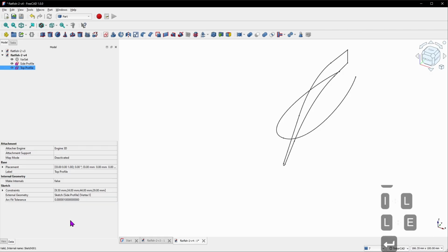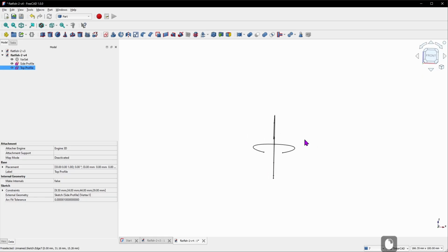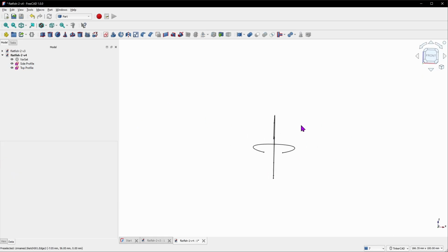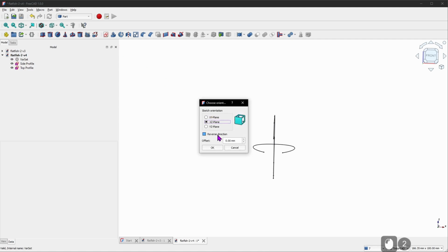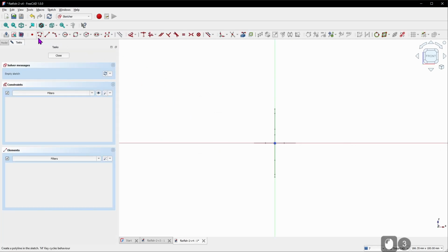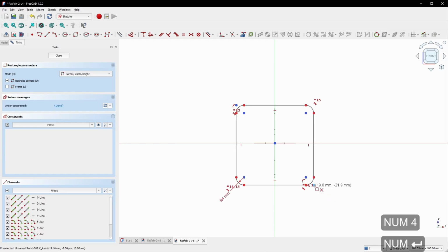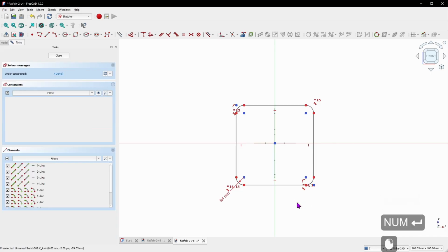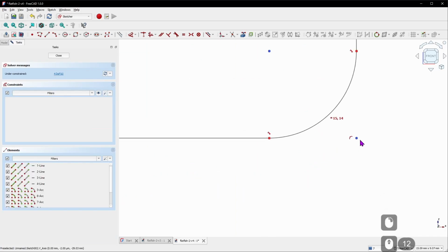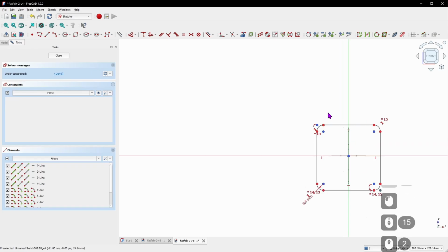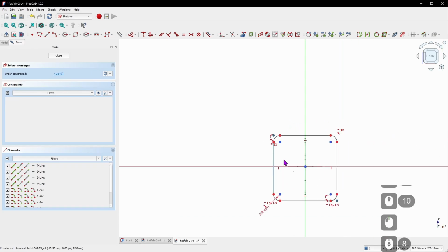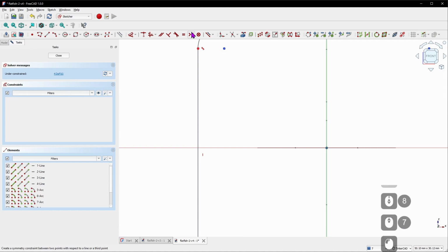We're going to be using the curved array from the curved shapes workbench again. And so we need one more profile, which is going to be the front profile. Let's create a new sketch for the front profile on the XZ plane. Here we're going to come up here to the rectangle and choose rounded rectangle. And when I drop a rounded rectangle, it asks me for a number and I'm going to type 4 and hit enter. And that's the size of my radius. So then I'm going to take these little helper points on the outside of these arcs, that one down there and this one down here, and select the origin and make it symmetrical.